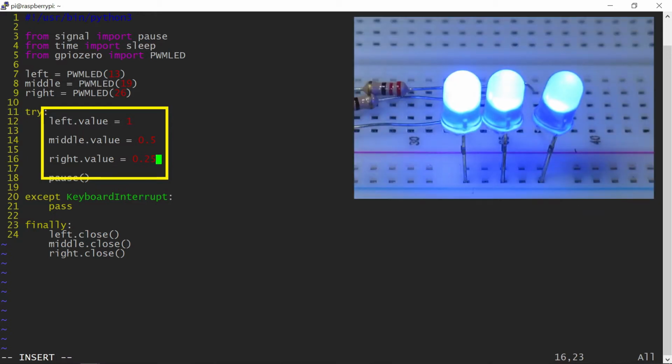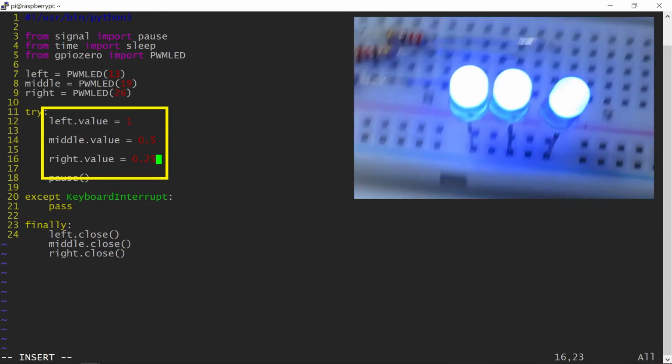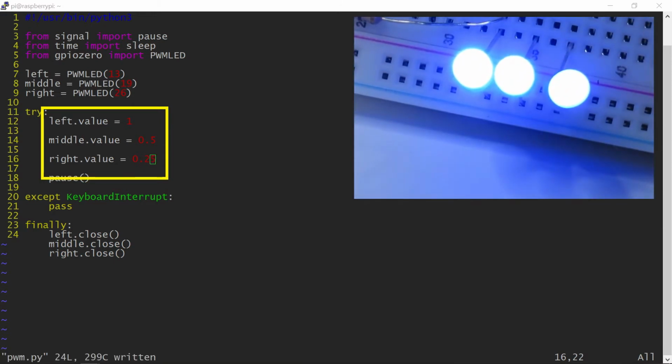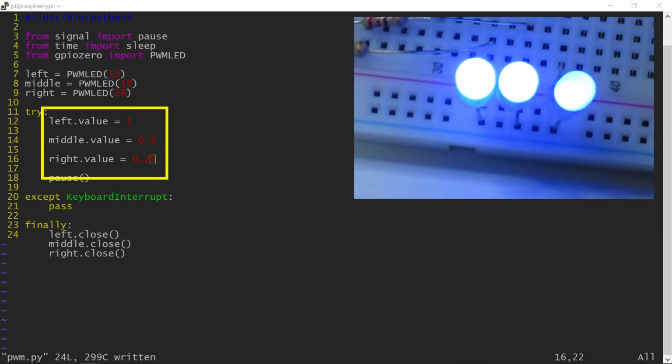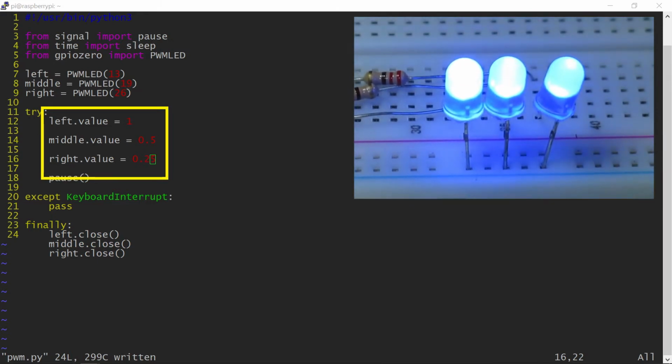My example sets the duty cycle at 3 different levels, from 100% on the left to 25% on the right. If you really look at them, the brightness is not that different. That's because LED brightness follows a logarithmic curve when using PWM power. This makes the value property difficult to use, as it is hard to predict what the relative brightness will be for a given duty cycle. This is particularly problematic when attempting to have gradual changes the way the pulse method works.